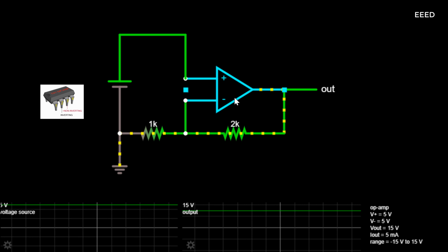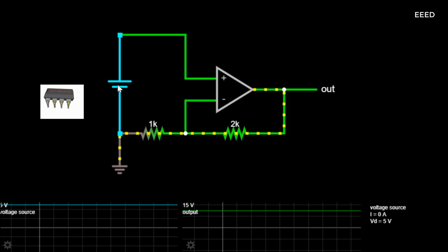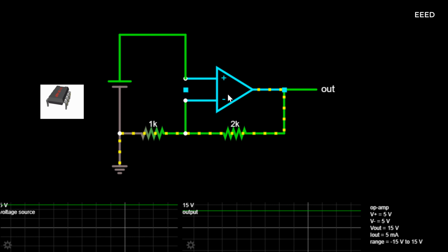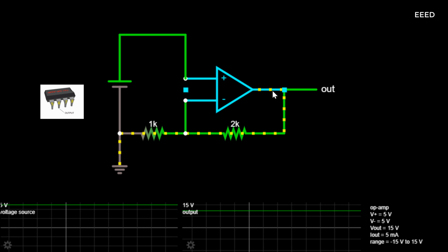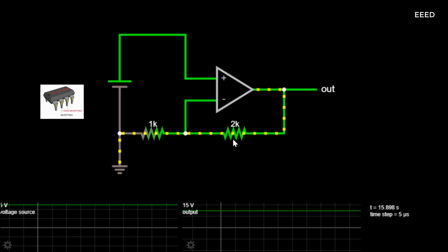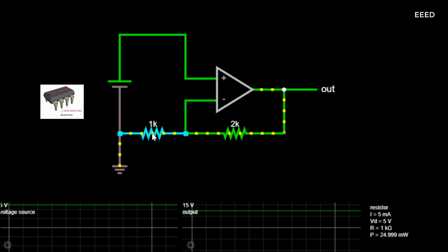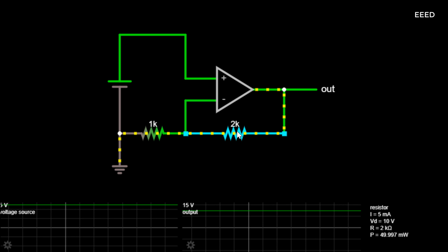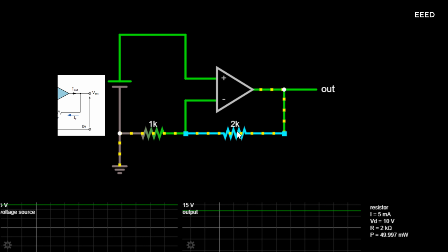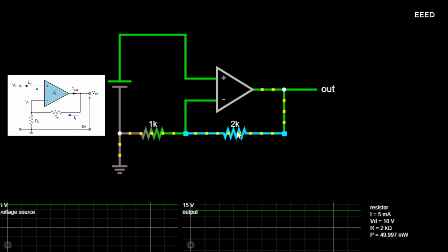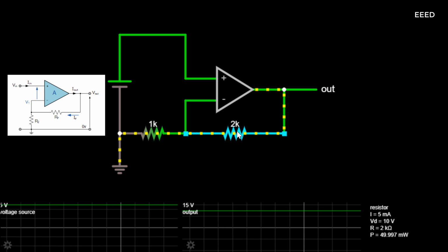Feedback control of the non-inverting operational amplifier is achieved by applying a small part of the output voltage signal back to the inverting input terminal via the RF, R2 voltage divider network, again producing negative feedback. This closed-loop configuration produces a non-inverting amplifier circuit with very good stability, a very high input impedance, RIN approaching infinity, as no current flows into the positive input terminal (ideal conditions), and a low output impedance, ROUT, as shown below. Non-inverting operational amplifier configuration.